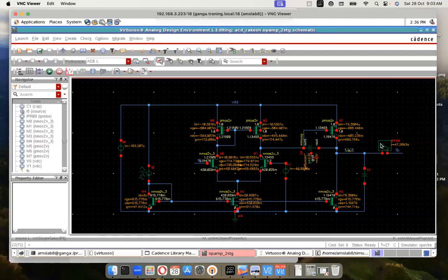For the time being, let's also look at the output voltage. This is supposed to be a unity gain feedback voltage buffer, meaning the input is 1.2, output also has to be 1.2. But is it the case? You see the input is 1.2, clearly because it's an ideal voltage that we provided. On the other hand, the output voltage is 1.194, meaning the Vout node is 1.194.